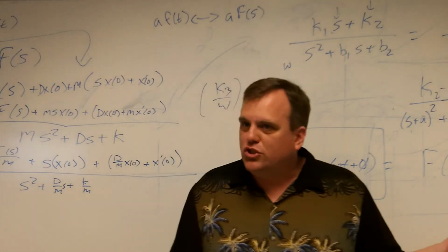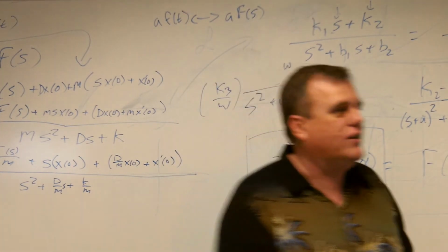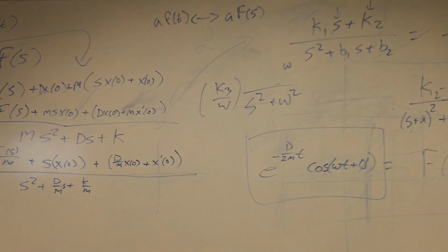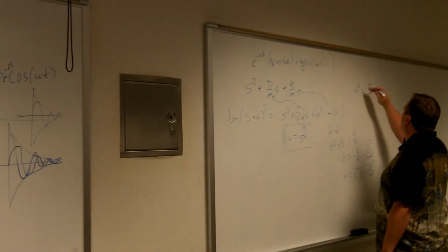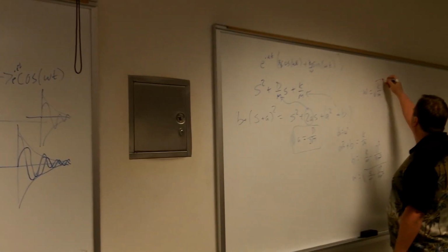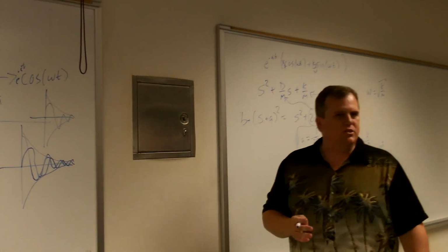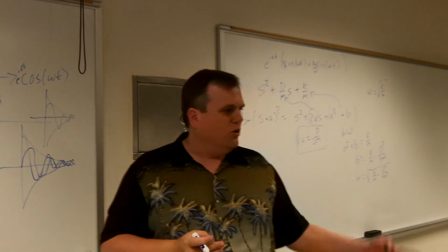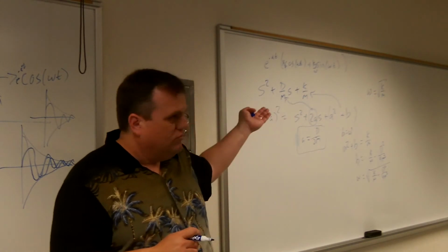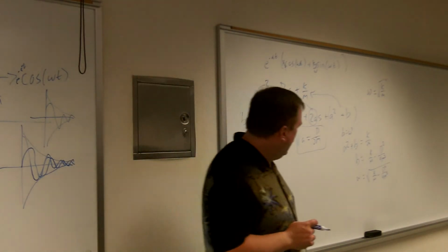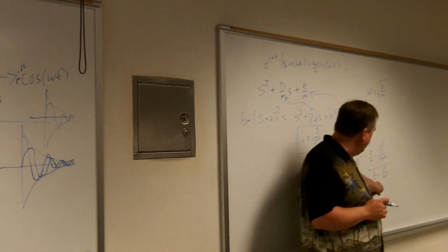is my frequency squared. So this is where you get the physics result, because they always give you no damping. What they get is that omega squared equals K over M. And then you take the square root, and you get that. And that's Physics 221 when they get to these systems. Right? They always give you that result. That's the undamped one.